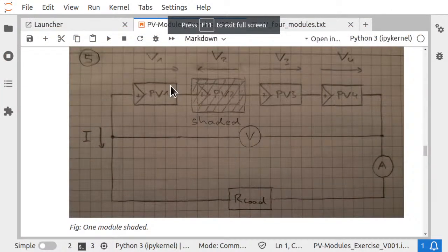What then happens is these are still generators. They are generating energy from irradiance, from your watt per square meter. There's amperes coming out of it, and voltage. And if one of them is shaded, this is a battery, this is a battery, and that is a battery. What now happens is that this here becomes a consumer.